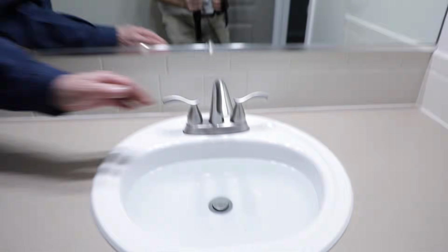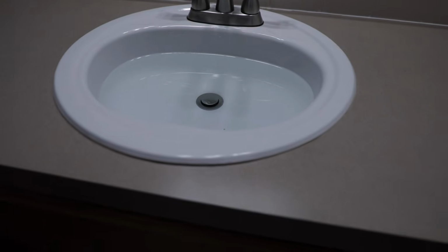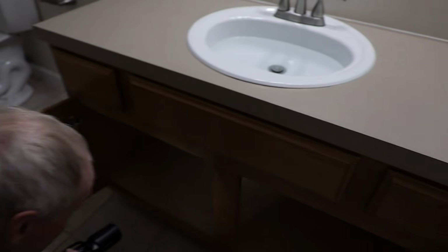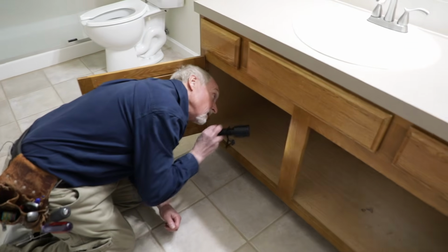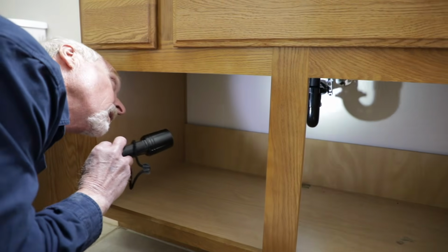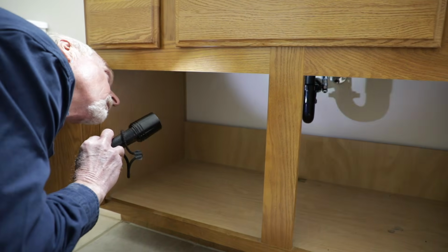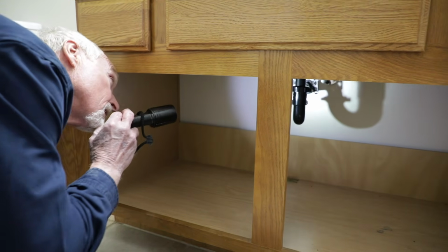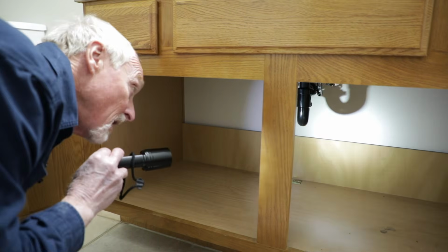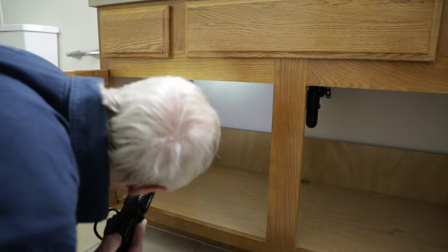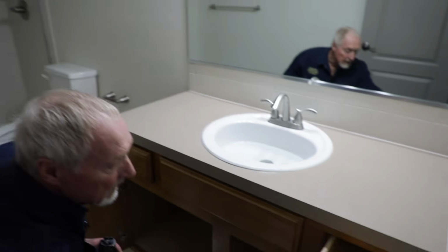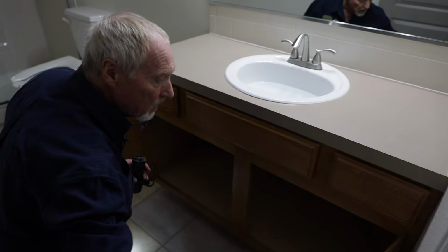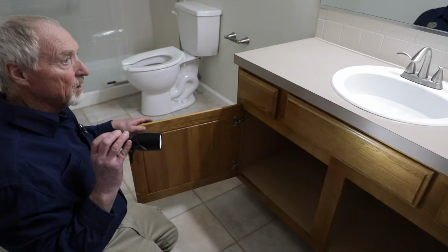So now I have my sink full of water. I like to release the water in the sink. That pressurizes the drain, and if it's going to leak, this will make it leak. And it is not leaking, so we look very good here. So we have stopcocks or shutoffs on the water supplies, which we always want to see to isolate the sink. And while I'm at it, I'll check to see if drawers work. And dead front there. And hinges on our doors are good.